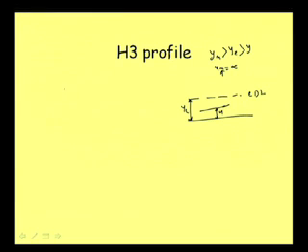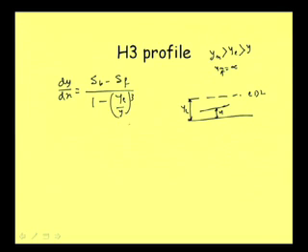And now we can have dy/dx is equal to SB minus SF divided by 1 minus (yc by y) whole cube. Again we are writing this for wide rectangular channel.